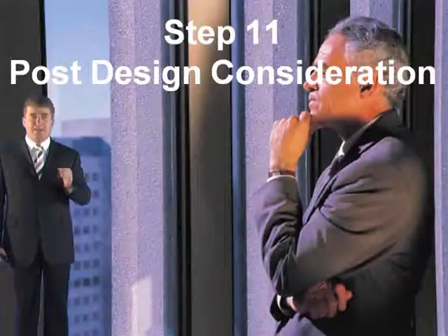The final check you need to carry out is step 11, which is the post-design considerations. In this case, you would ensure that weather conditions would not have an adverse effect on ventilation and that the pitch of the roof is not greater than 30 degrees. In other words, you've got to look through the wind criteria, you've got to look at your curtains, make sure they are not going to deflect, and you've got to look at tall buildings in that area. Those are the sort of things I would expect you to look at in the post-design considerations in step 11. And that completes this exercise.